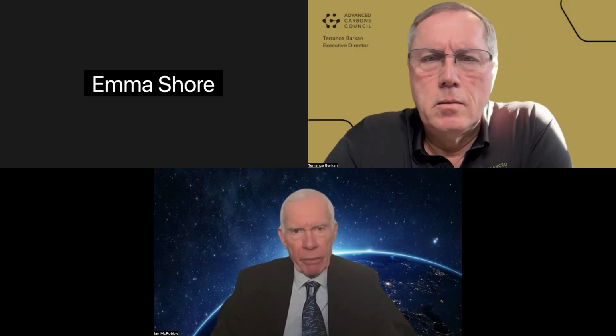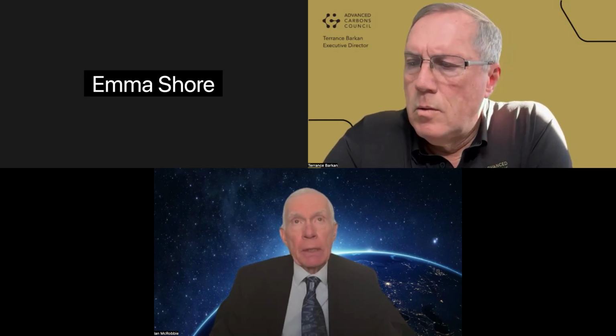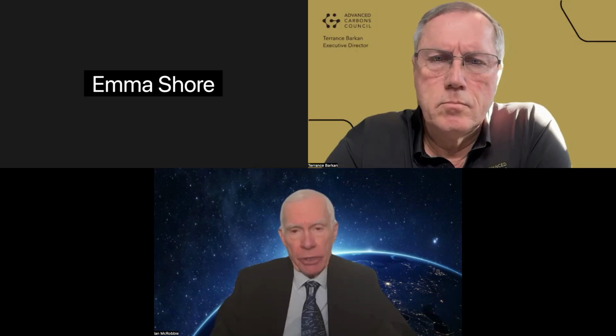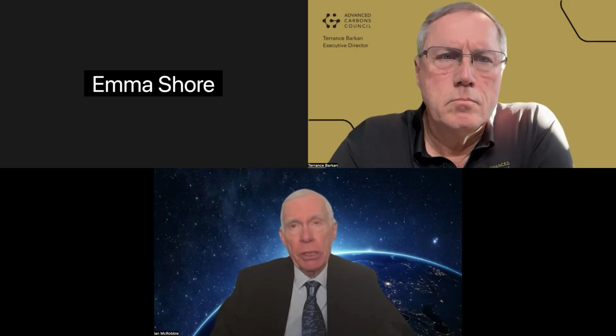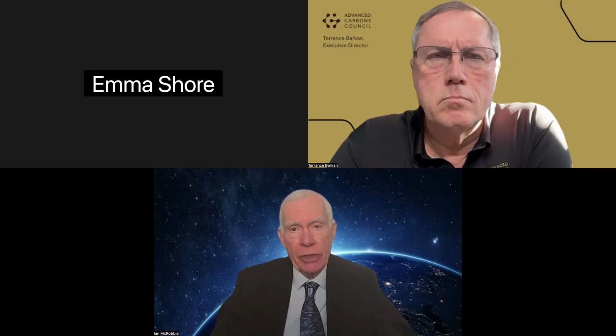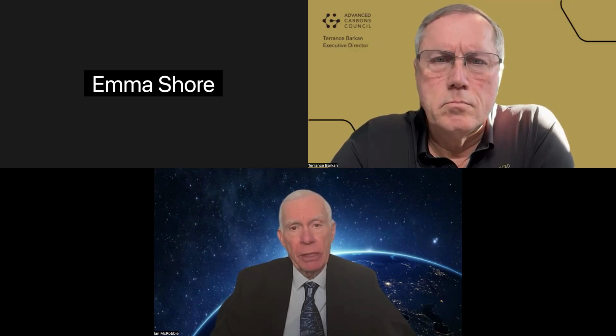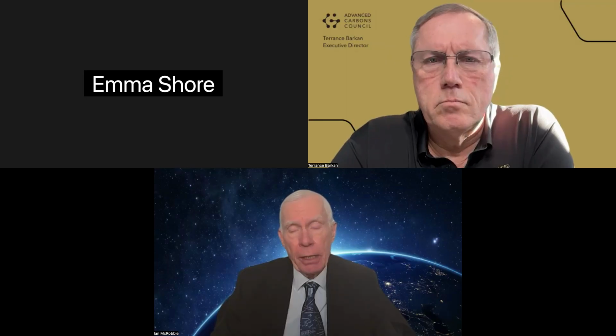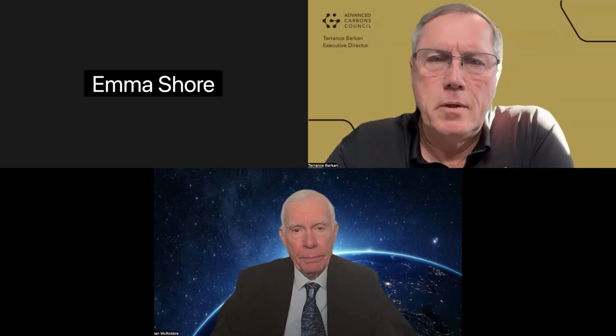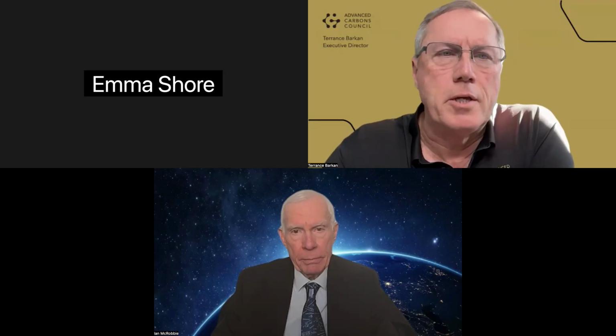Excellent. So if I could add a bit more colour to that, the temperature of the ferrocene is critical, and the choice of the catalyst in terms of thermal decomposition temperature. One of the areas that we're working on now is to look at different catalyst systems with different thermal decomposition points. And what we've found is, because we make a range of ferrocene derivatives, that we can change the diameter of the carbon nanotubes, but maybe that's a talk for another time. It's good to know you have that tunability of the materials, and it can influence that, because obviously people are trying to make different iterations of either multi-wall or single wall, depending on what the end application looks like.